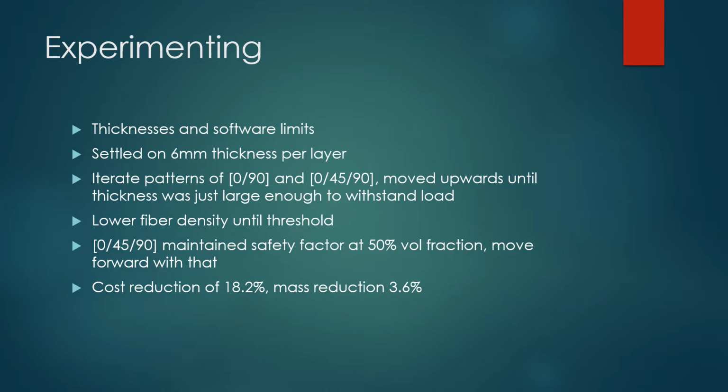Experimenting. So first we ran into some thickness and software limits. Industry generally has lamina that are 0.6 millimeters thick. However, given the forces we were given and the conditions of our materials, we literally could not fit enough lamina into a laminate that would bear those forces.